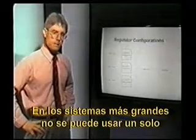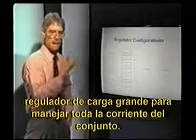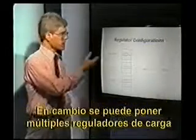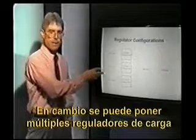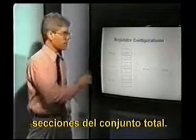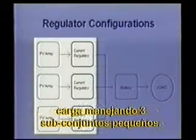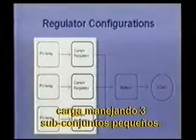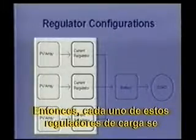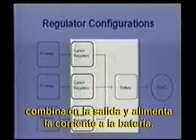For larger and larger systems, we may not be able to simply use one large charge regulator that can handle all the array current. We may choose instead to put in multiple charge regulators that handle subarrays, small sections of our total array. In this case, for example, we show 3 charge regulators handling 3 small subarrays. Each one of these charge regulators then combines in its output and feeds the current into our battery.